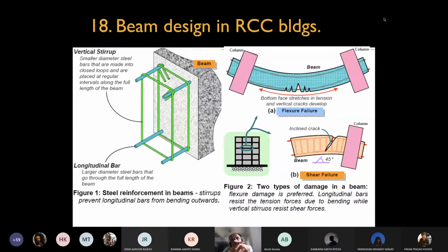If you imagine it in very slow motion, the first slab drops onto the second slab. The second slab, again, is not able to take that stress, and again there is a shear failure. It is as if there are needles placed below, and the whole thing gets punctured. The slabs start getting stacked one above the other.